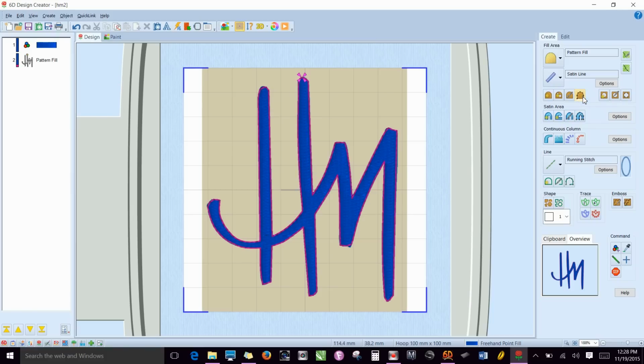This one here is the one I use the most. Okay, again, you're going to set up what you want for your pattern fill and your outline, if you want a line at all. This one's going to allow you to manually place your nodes. See all the little nodes on there? So you're going to click and click and click, left click. And if you want to make a square node, you're going to control and left click, control left click, control left click, control left click.